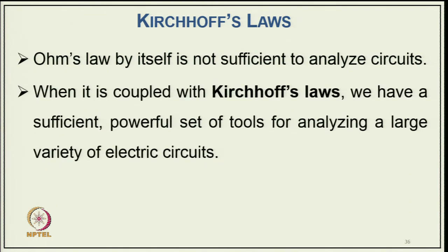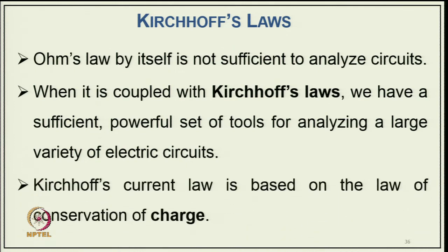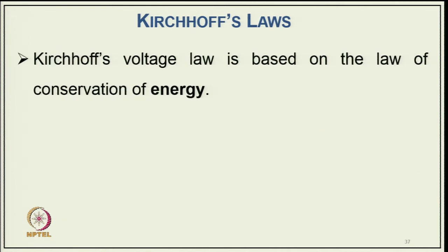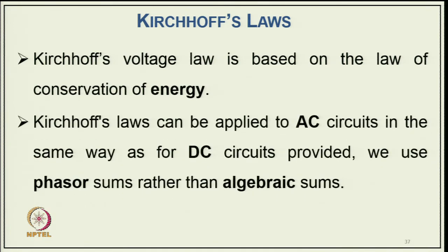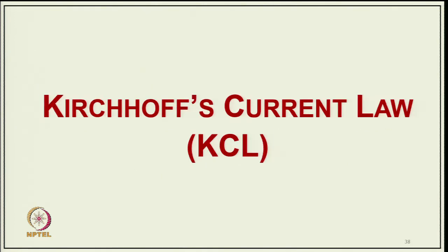That is why Kirchhoff's laws were devised. When coupled with Kirchhoff's laws, we have a sufficiently powerful set of tools for analyzing a large variety of electrical circuits. Kirchhoff's current law is based on the law of conservation of charge, and Kirchhoff's voltage law is based on the law of conservation of energy. Kirchhoff's laws can be applied to AC circuits in the same way as for DC circuits, provided we use the phasor sum rather than the algebraic sum in an AC network.